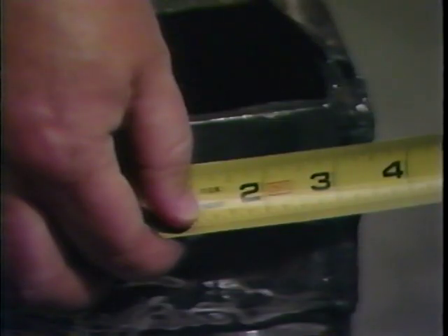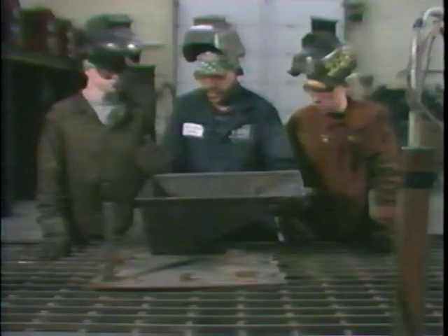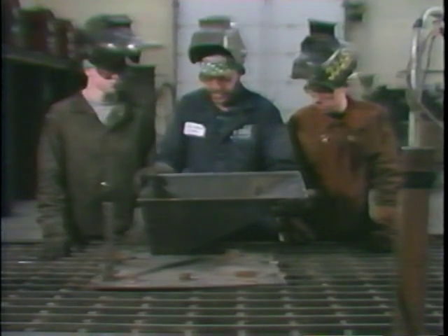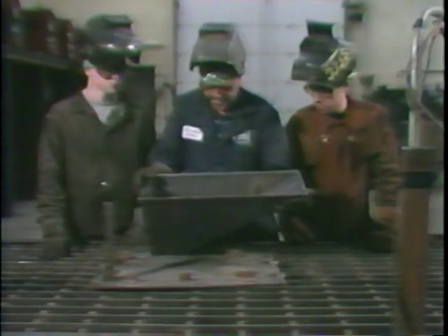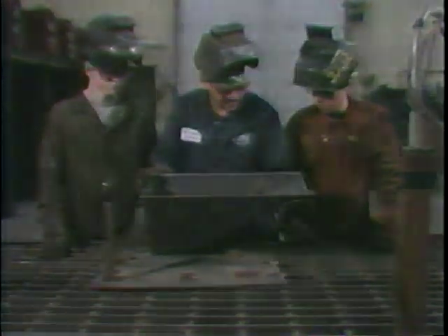The blueprint for this 4-sided hopper specifies that the top width of side A is 11 1/2 inches. The bottom width is 3 1/2 inches. The height is 12 inches, and the slope is 14 9/16 inches. If during the layout process, the specified dimensions for any one of the 4 hopper sides had not been maintained, the hopper could not have been accurately fit up and assembled.